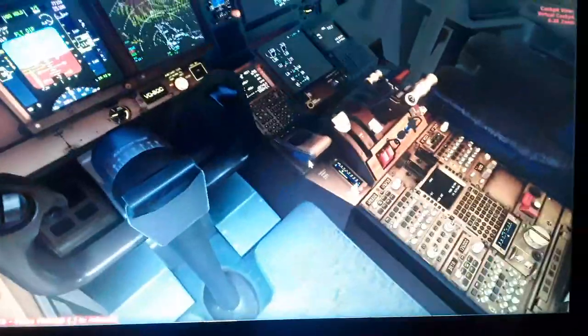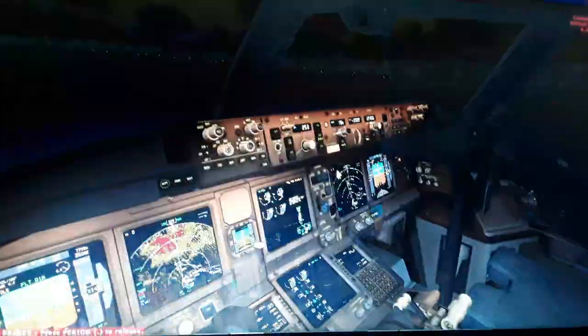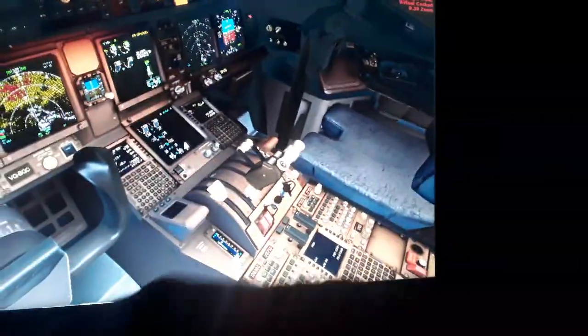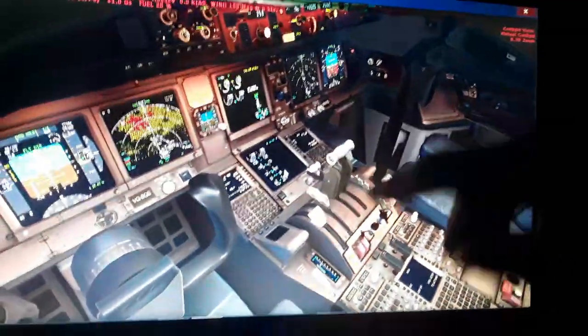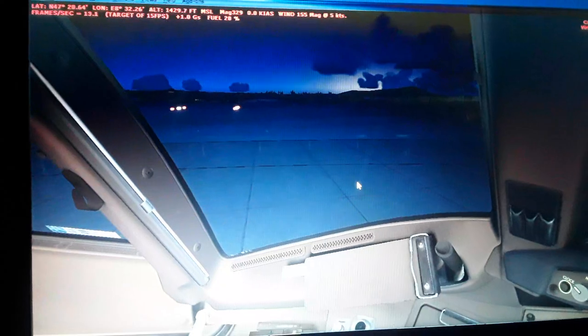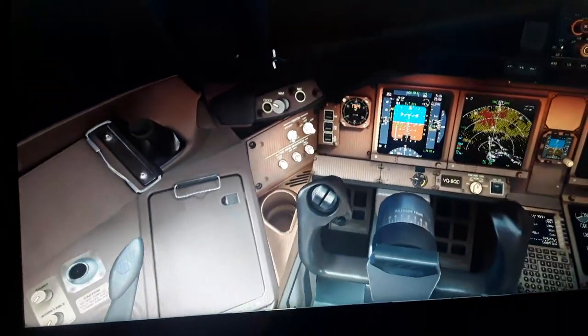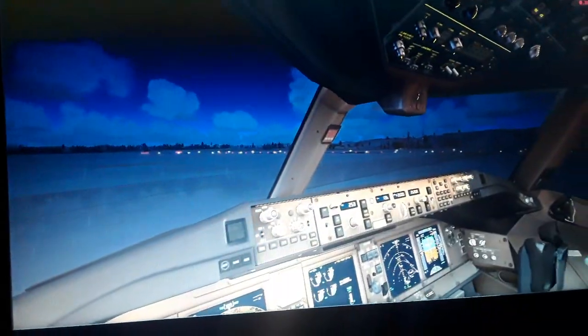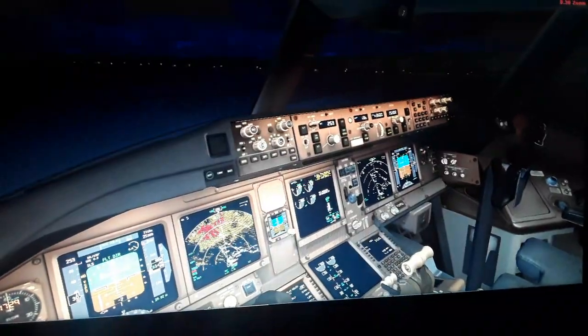We have set the aircraft, the flight plan is ready, so parking brakes disconnect, and we go for the runway for takeoff. Advance the thrust levers like this. We take the runway clearance from the air traffic control, and we start moving the aircraft.